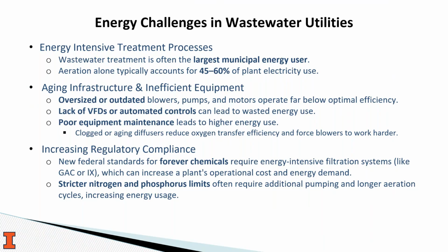Without technologies or additions like variable frequency drives, or VFDs, or updated automated controls, wastewater plants can end up using a lot more energy than necessary, and poor maintenance only worsens this effect. If you don't address clogged diffusers, for example, that can impact oxygen transfer rates, which can force blowers to work harder, driving up energy costs.